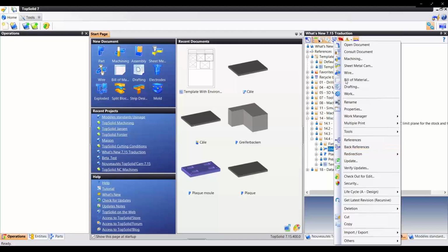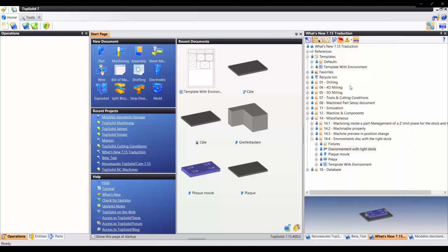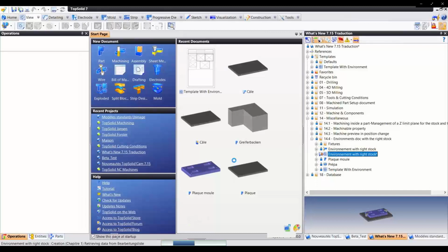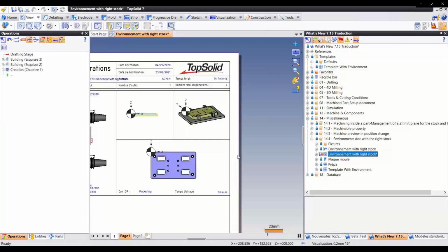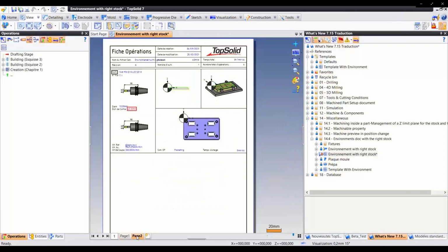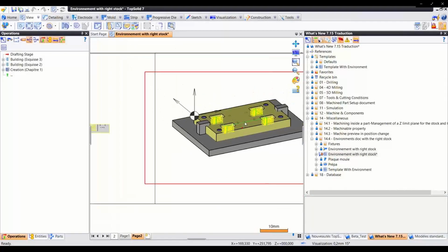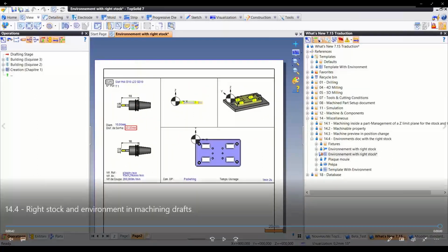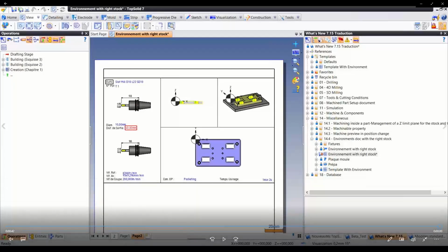Now if we go ahead and just make a quick setup sheet for this, and we'll choose that template. There is op 10, for example, and there's op 20. So it's automatically showing the two setups. Now, these are also in the same CAM file. It's super important to understand. You can't get both of those automatically from one drawing unless they were both in the same CAM file.